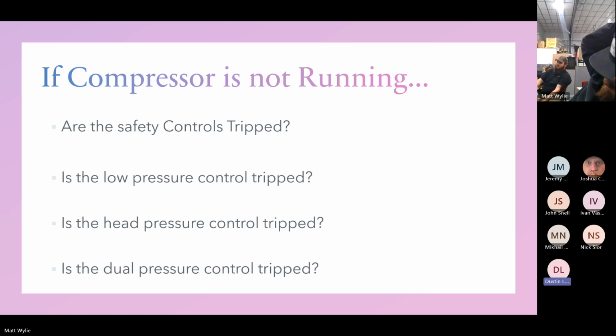On 208, if your switch is open or closed, it doesn't matter. You're going to have 120 volts to ground on both sides. So you have to check across your switch, and across your load, like if it's a motor. If it's a 208 volt motor, great, you have 120 on one leg of power and 120 on your other leg. But do you have 208 across the load, or do you have 0 and your switch is closed?